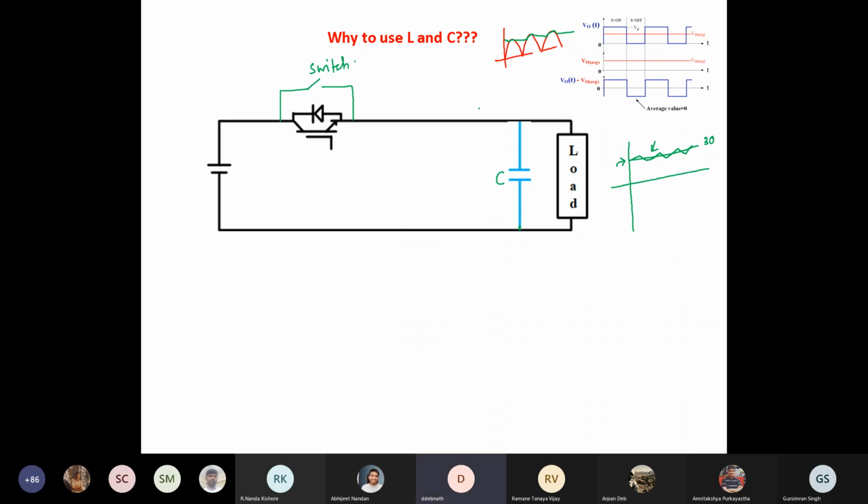Go ahead. You want to suggest anything else? There is no resistance in the charging path. Like you said, it's an ideal switch. This is the biggest problem, right? In electrical engineering, there are two main constraints. Two voltage sources of different values should not come into parallel, right? And an inductive circuit should not be broken. Inductor current should not be discontinuous. These two golden rules, every point of time you should remember.